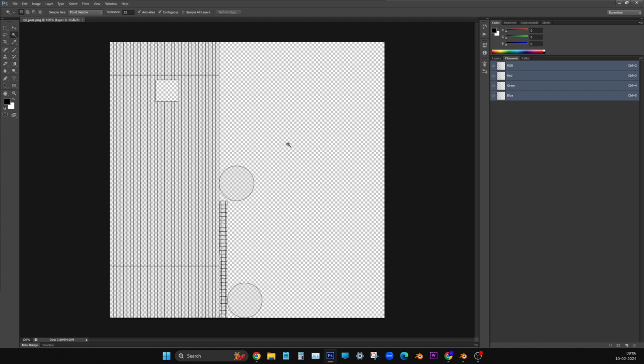Now whatever we paint here, when we apply it as a texture in Blender, it will show up. So now you know that we have to unwrap the mesh, make it a flat bed, bring it to Photoshop and paint on that flat bed, then save it as JPEG or TGA or whatever, and apply it as a texture in Blender. This is the process for UV unwrapping and texturing. So till this level you can do. I will unshare. You can share your screen.